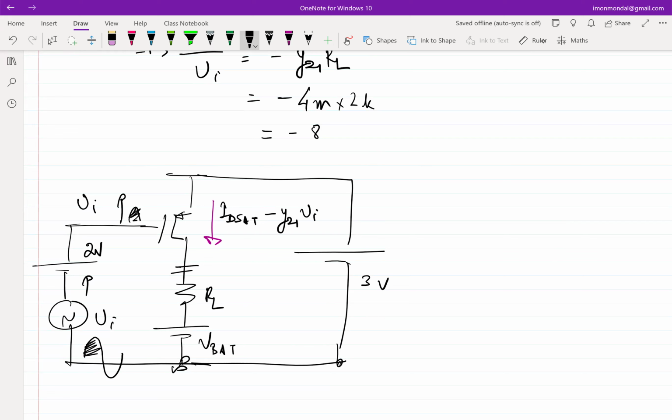It's not as if the magnitude of the incremental current has increased, but the total current through the transistor has decreased. So if I observe this total voltage, what will I see? Initially, it was probably at, I don't know, maybe 1.9 volt or something. And when input increased, what's going to happen to the total voltage? It is going to decrease. And since it's 180 degrees out of phase, the input does like this, and the output does like this.